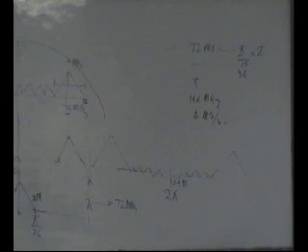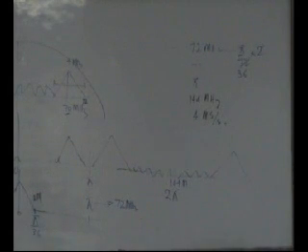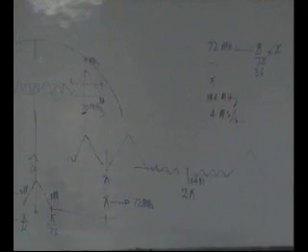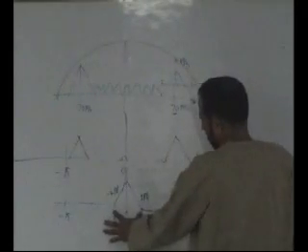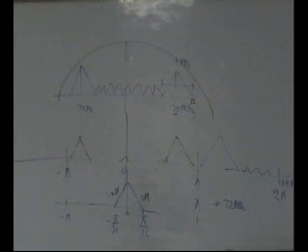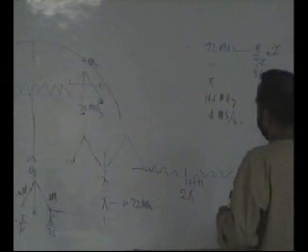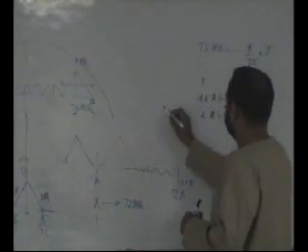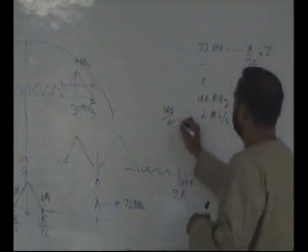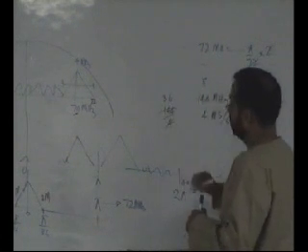And this requires that once you do this operation, you must throw away redundant samples. As soon as you get this, the very first thing you must do is throw away samples. Must. So this is really what is done: 144 megahertz, and because you don't need this many samples, if you divide it by 4, 36.